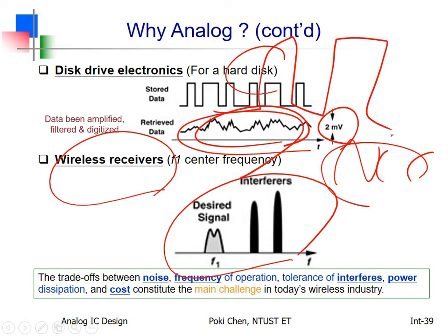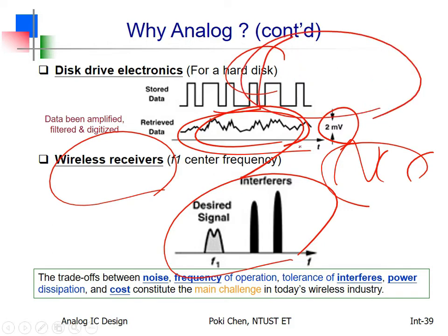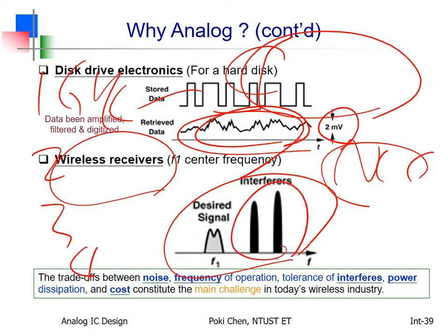This is too dangerous because for such kind of digital wave or square wave, you have harmonics. So if you transmit this at 1 gigahertz, it means what? The harmonics, 2 giga, 3 giga, 4 giga, everything is in the air. You have a lot of interference to the other base station. That is really harmful. Our officers and the other company will kill you because you have a lot of pollution to the RF spectrum. 你污染了整个 RF 的频谱，你会吓死人。